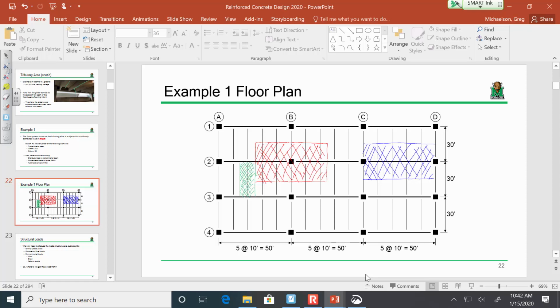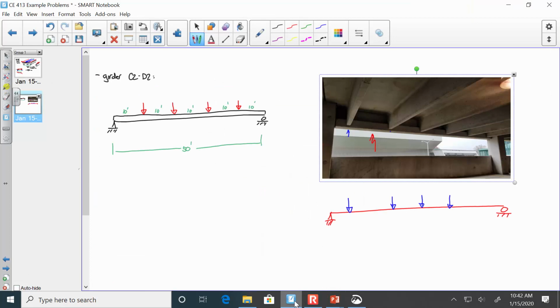Make sense? So I would propose that the analytical model for the girders, this is going to be 2R. 2R, or R equals 3,000. 2R is 6,000. Now, I tell you what, if you want to make sure that your notation is correct, maybe call these RBs. RBs. So that way it's beam reaction. I wasn't super precise with my notation. We'll just say RB for beam reaction.